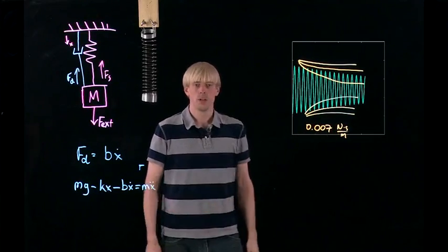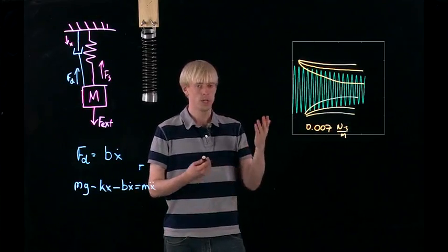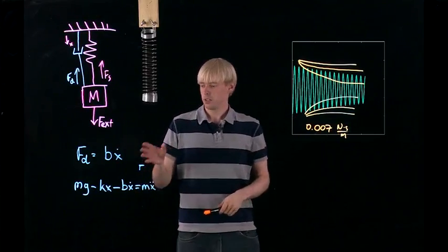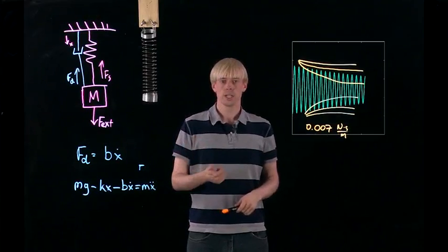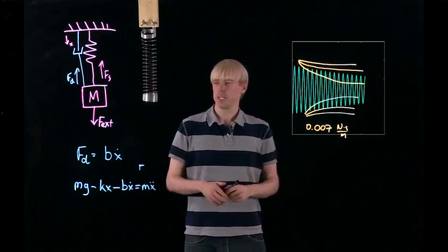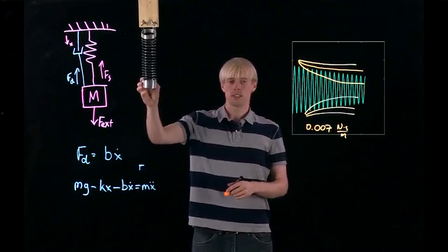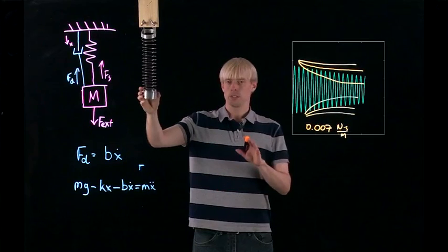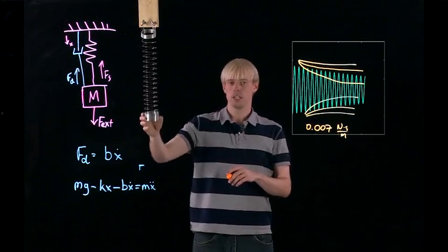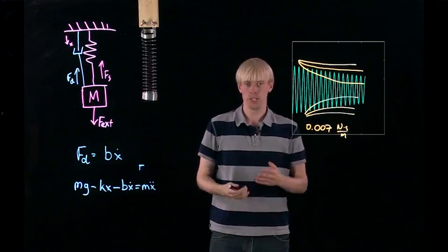So depending on your system, you can figure out if that is a reasonable term, if that is too high, too low. And you can also check out your spring constant and mass parameters as well. If your spring and mass are off, you might see that your simulation is either going up and down too fast, too slow, and if your parameters are just right, it should stay pretty much in phase with your actual Slinky or spring mass damper system.